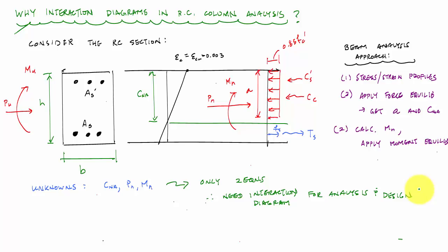All right. Why do I not apply it about the neutral axis? Where do I apply it? Does anyone remember what it's called? Where does that load resultant go? It happens to be the geometric centroid here because my cross section is symmetrical, but it is also called the plastic centroid. So here we apply the loading at the plastic centroid. This is where we're going to measure our eccentricities. All right. Excellent.